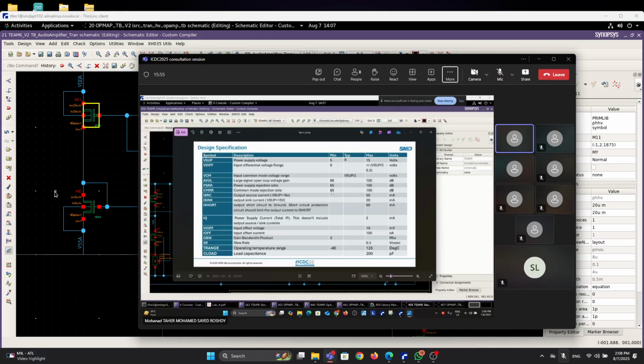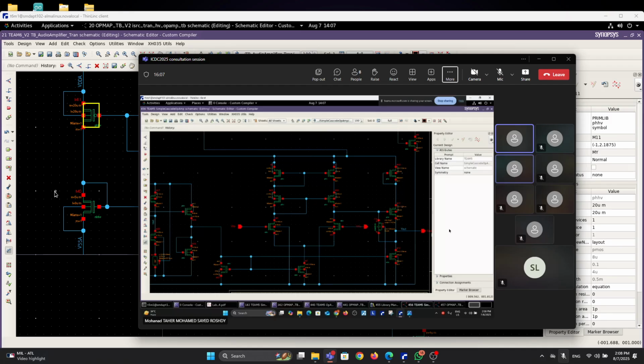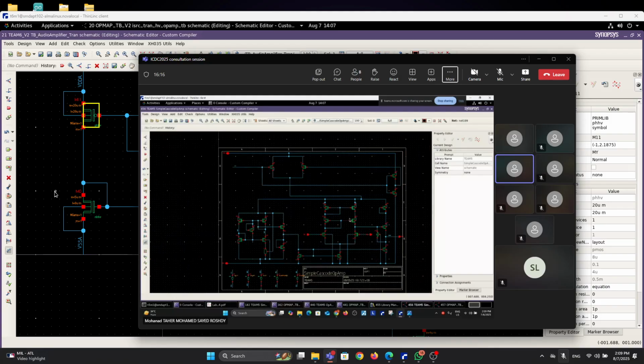I'm not sure. Is it just, how to say, magnitude, absolute values? Magnitude. Okay. Because if this one is positive, your common mode noise will affect everything. So I think that should be negative. And I think in my test bench I put a minus in front, so you can tabulate your data in positive values.